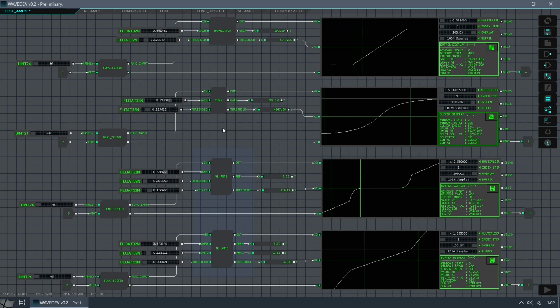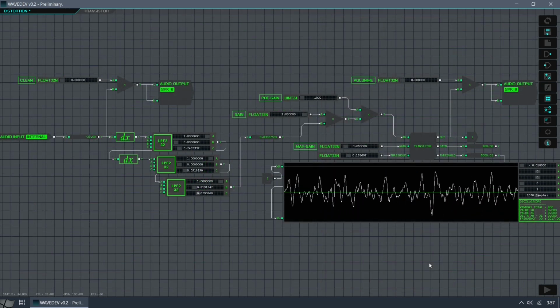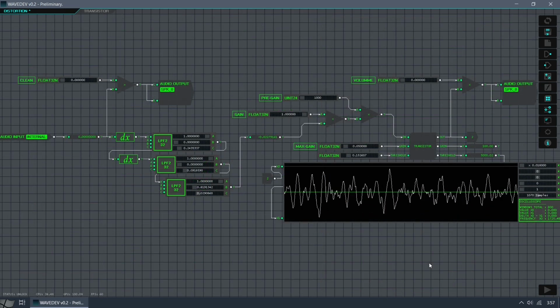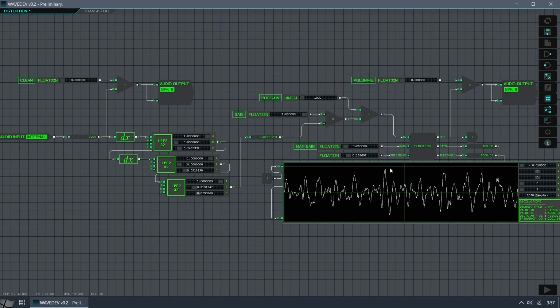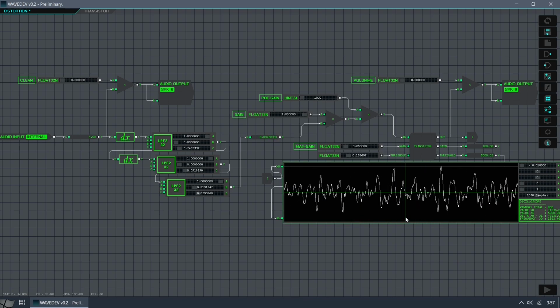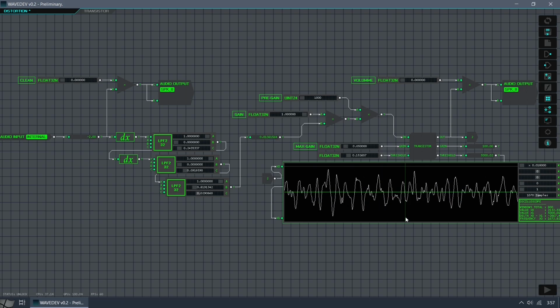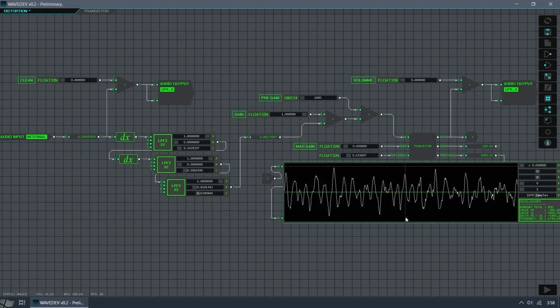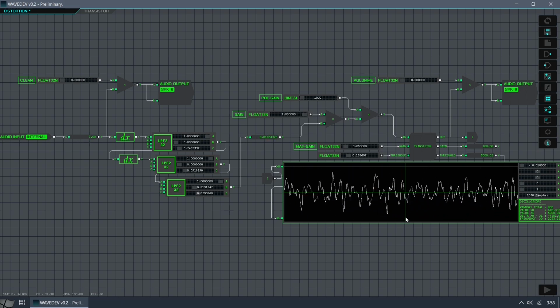Your noise level should be minimal if you want to use this technique, because it can easily introduce artifacts into the sample as the threshold moves away from zero. In short, if a 300 coefficients filter wasn't even able to scratch this signal, and the use of noise gates may introduce artifacts into our effect, then there's little chance of overcoming this problem in the digital world.